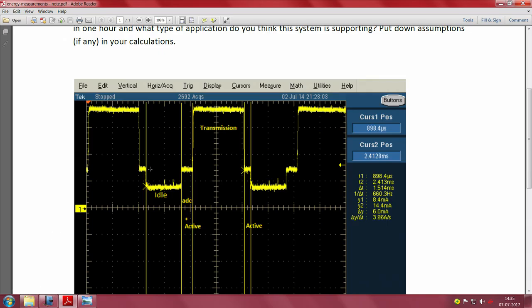Then you wait for a small duration, which is for getting an acknowledgement. The reception current, for keeping the state machine in reception mode, is lower compared to that of the transmission, and it is also waiting for a very short duration. Then it goes to an idle period and then goes back into sending out the next packet and then the next packet.